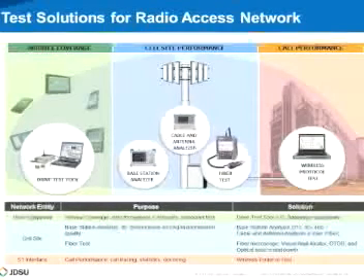On test solutions for the radio access network, I believe that service coverage is one of the most important parts of doing an RF design. That means using actual users' handsets to verify coverage and throughput, because this is often the best way to relate to those who own or manage real estate, to help them understand exactly what's taking place using terms or measurements they might be familiar with based on their own day-to-day usage of technology.